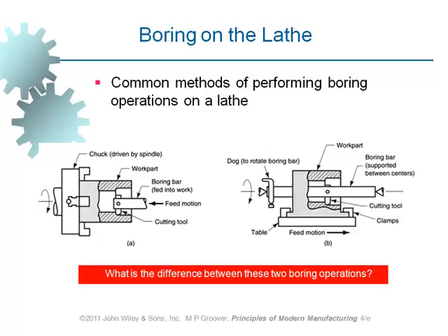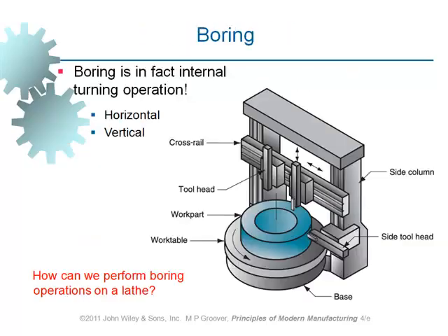So, two different methods which are used for performing boring process on a lathe. But of course, as you see here, there are some boring machines which are specifically designed in order to perform internal turning operation on really big rotational parts. The way that we do the computation of cutting speed, etc., is similar to turning. Very similar to turning.